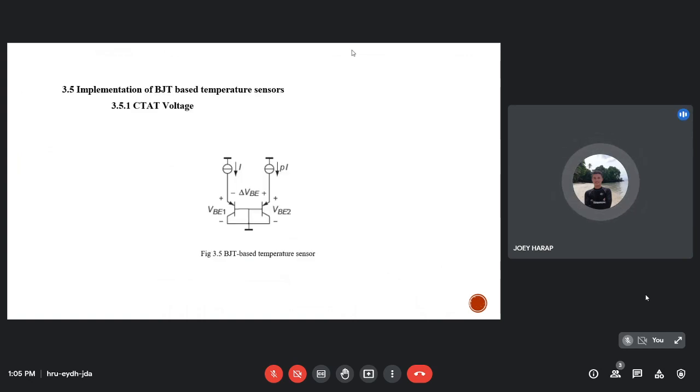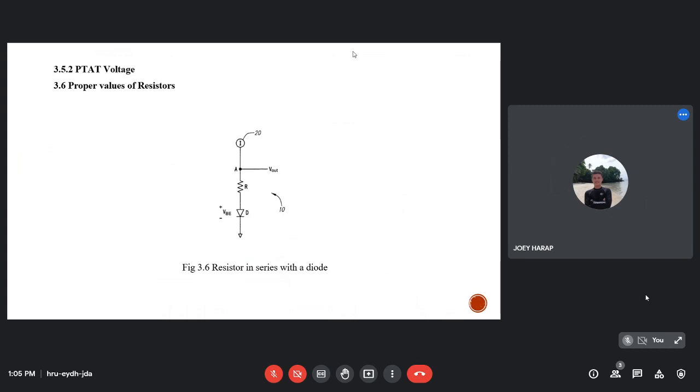And of course, a diode in this figure with a resistor in series is also taken into account, because a diode D, which may comprise a diode-connected transistor, in series with R, is forward biased in response to current I to provide a CTAT voltage V. Taking the output voltage V from node A provides a sum of the CTAT and PTAT voltages, reducing the value of R appropriately.